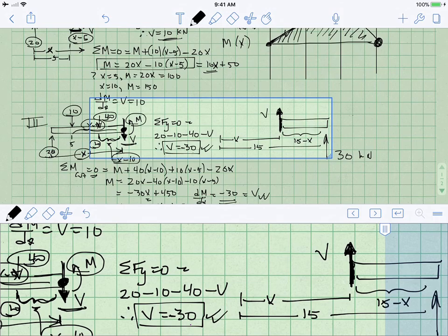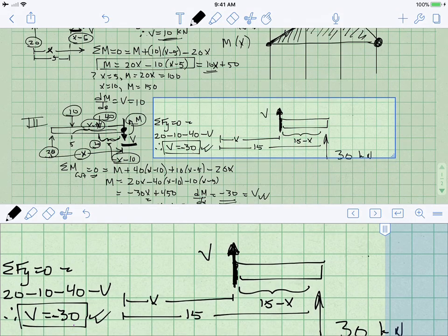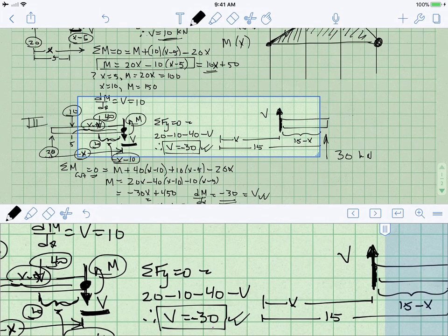By convention, the left-hand side of the beam has a positive shear pointing down, and the right-hand side has a positive shear pointing up. Similarly, what's going on on the left-hand side of the beam must be counteracted at the right-hand side. So I write positive moment like that on the right-hand side of the beam.